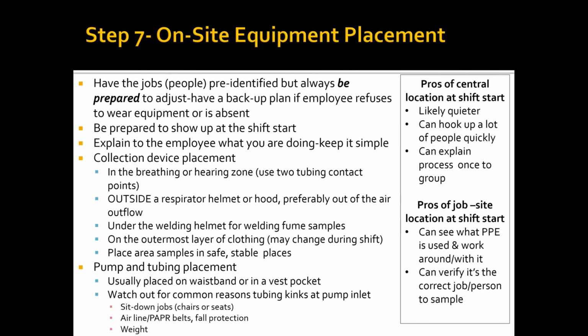Pump and tubing placement, usually the pump goes on the waistband or in a vest pocket. If the person's wearing coveralls, that can be a little bit of a challenge. Sometimes the tubing is too short. And look out for reasons that the tube could kink at the pump inlet, because that'll flow fault the pump, and then you've got, again, interpretation issues or short samples.